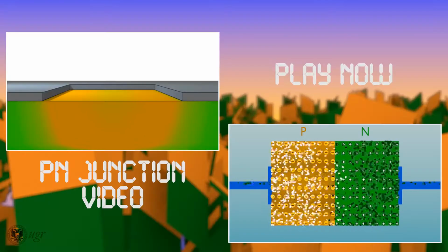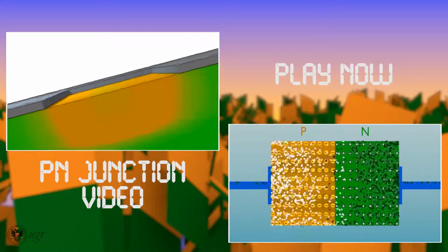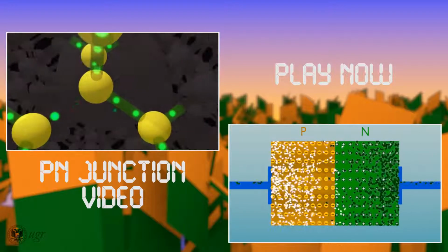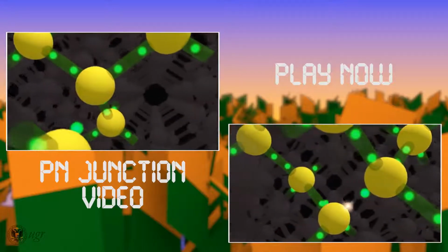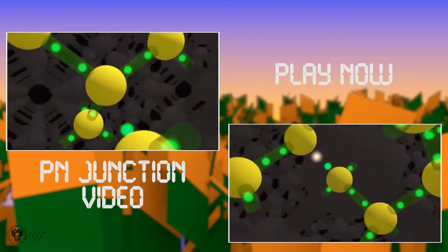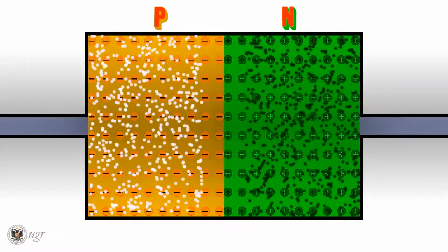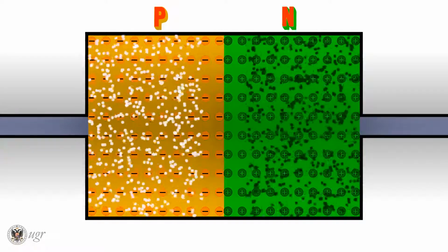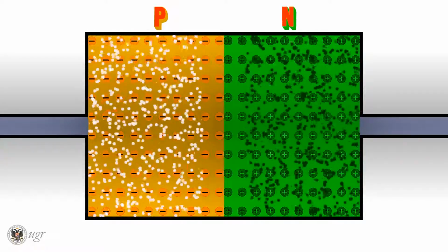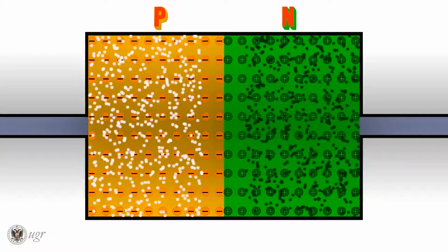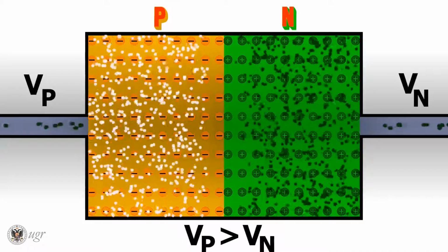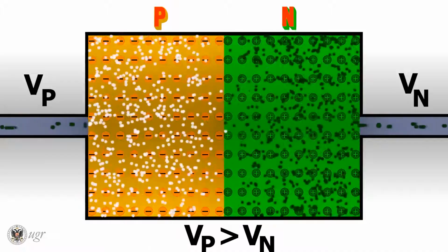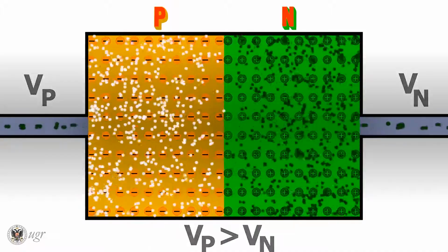Primarily, the basic structure of an LED was a p-n junction formed by specific semiconductor materials. In the previous video of this series, where we presented the p-n junction, we could see that there are two charge carriers in semiconductors, electrons and holes. The p-n junction is a structure that, under certain conditions, can spatially separate electrons and holes. By forward biasing the device, which consists in applying a higher voltage in the P than in the N material, the current flows through the structure, causing the electrons and holes to meet in the same region of the space.